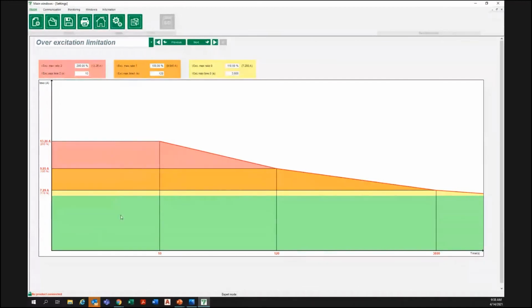So this green portion right here is going to come all the way up to 100% of the set point. It doesn't actually label the set point. This is not our full load current. Our full load current ends right here, and it's actually 6.63 amps. So this can be held for an indefinite period of time. It extends on forever.